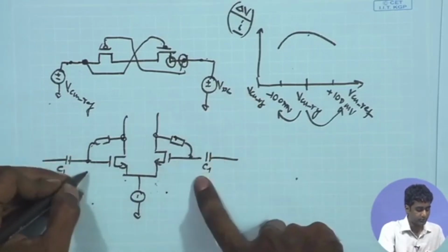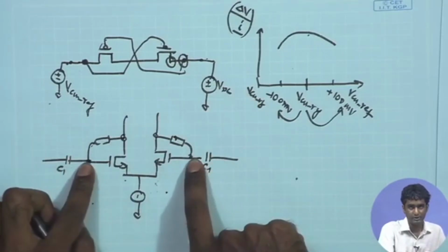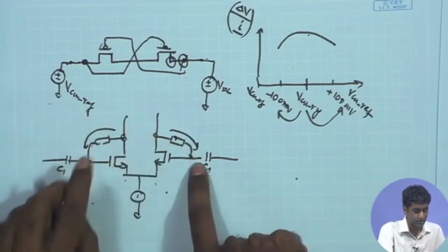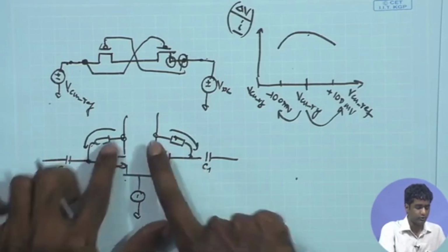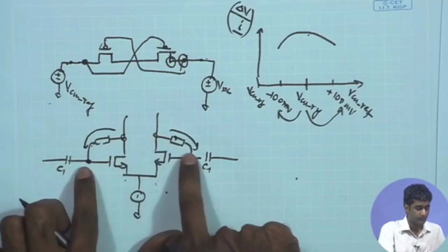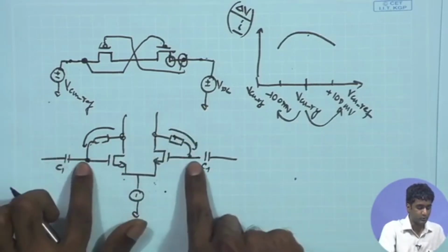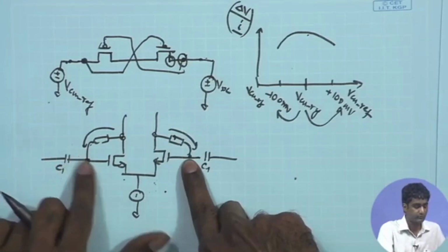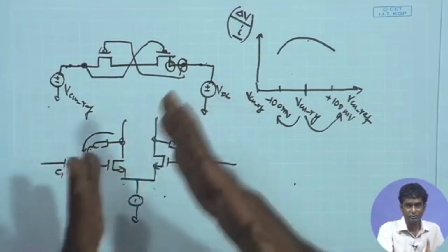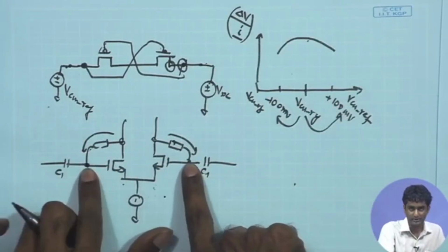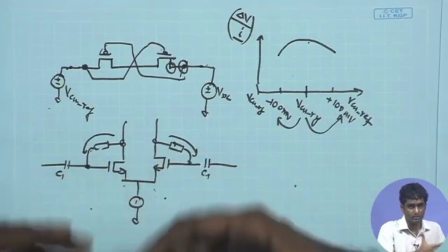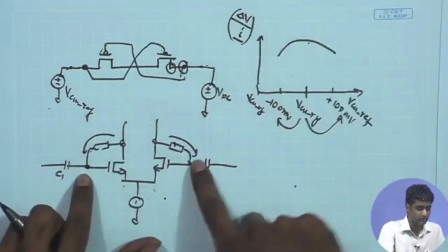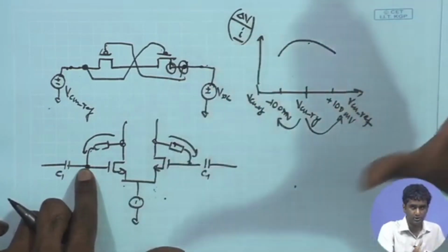So, in the transient simulation, therefore, this value may start from some arbitrary value, some arbitrary voltage, and it may take some time for this resistor to charge this voltage nodes to the values equal to the common mode output. So, in the transient, if you just calculate the RC time constant, it will be order of few seconds. Therefore, if you are trying to run transient simulation for few milliseconds in order to simulate your low frequency signal, it may not settle within that duration. And in simulation, if you try to run simulation for such a long time, seconds, to just allow this potential to settle, it is going to waste a lot of time.